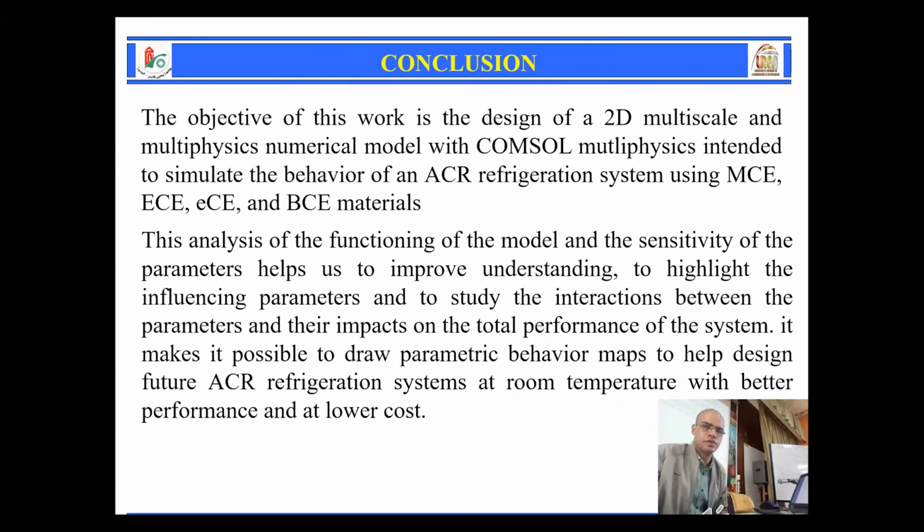Conclusion. The objective of this work is the design of a 2D multiscale and multiphysics numerical model with COMSOL Multiphysics intended to simulate the behavior of ICR refrigeration system using magnetocaloric, electrocaloric, elastocaloric, and barocaloric materials.